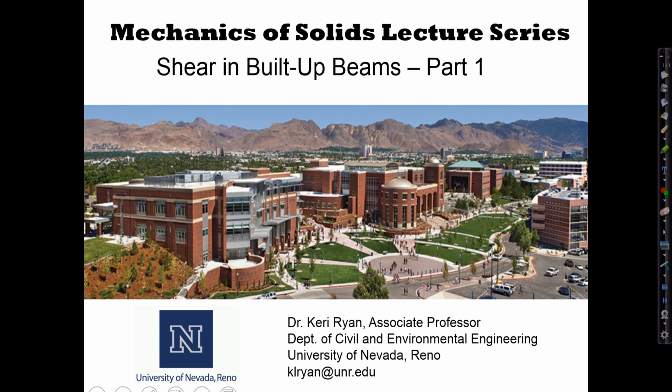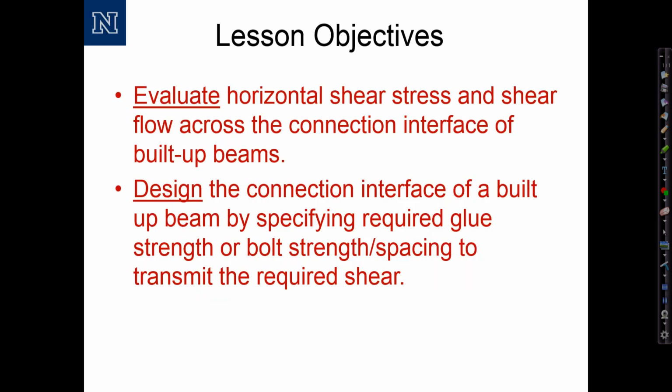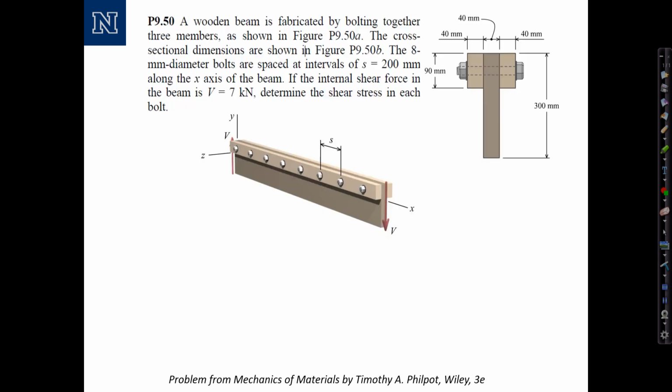In this series of videos, we're evaluating shear in built-up beams as it pertains to connection design. Our lesson objectives are to evaluate horizontal shear stress and shear flow across the connection interface of built-up beams. Then we can design the connection interface of a built-up beam by specifying required glue strength, weld strength, or bolt strength and spacing to transmit the required shear.